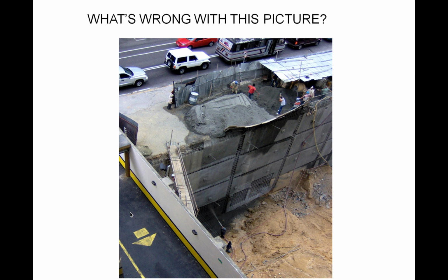The temporary platform looks like it has wooden slats, and basically when you have that, you need some kind of overlap between one slat and the next, so that you don't step on one edge and then the back edge of that comes flying upwards, like a seesaw. So those should have some overlap so that doesn't happen. It's just too many things here. Just unsafe. Don't do it.